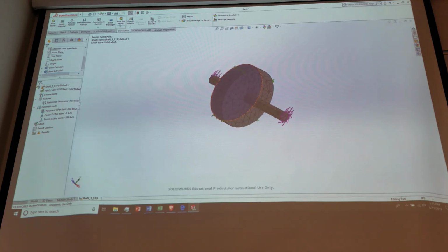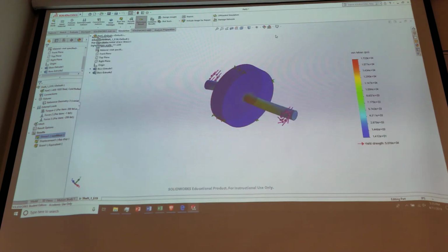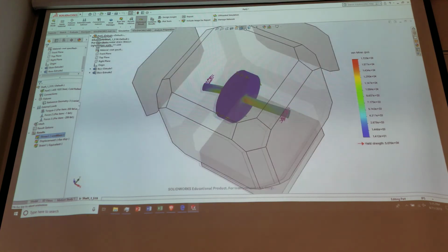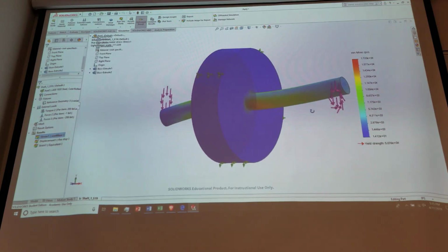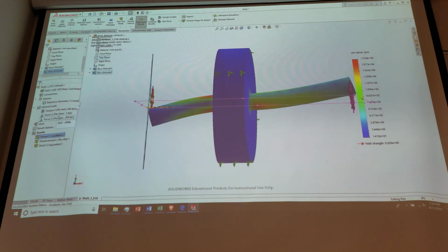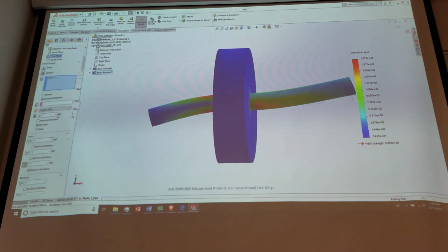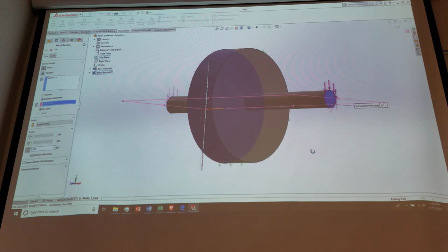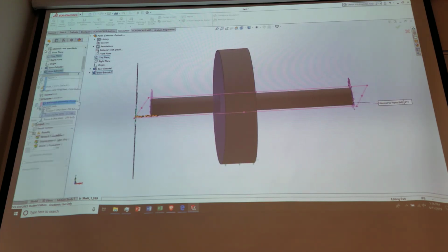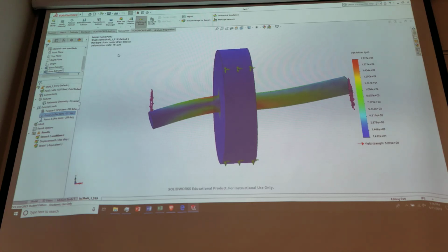Got a perfectly fine mesh there, and let's run it and take a look at it. And now I get the top here. Did I get my forces wrong? You have 1 pound force on. Oh yeah, -1, that's not a good thing. So for whatever reason, that didn't get right. So that one needs to be the 211. Okay, and is it going the right direction? It's going the right direction, yeah, okay. That'll probably help.